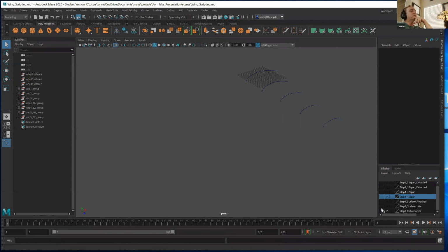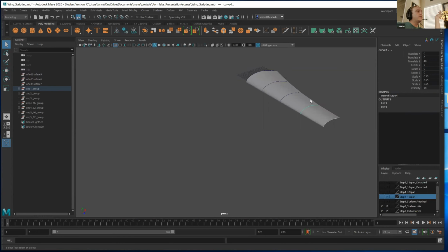So I've got a couple of layers here just to kind of quickly run through this. So when you take curves, you can do what we call lofts. And by the way, if you're in Fusion 360, Fusion 360 can do all this from the patch tool sets. Now, those lofts look like this, and all that is grab one curve, grab another curve, and in the modeling tool set under surfaces, it's called loft, okay?